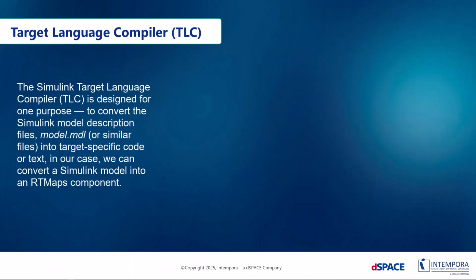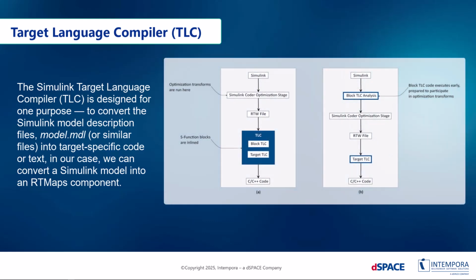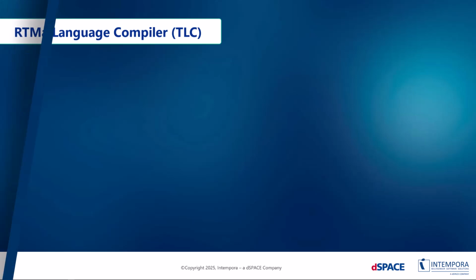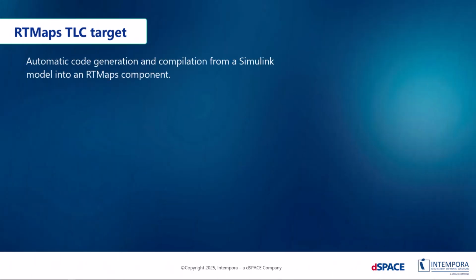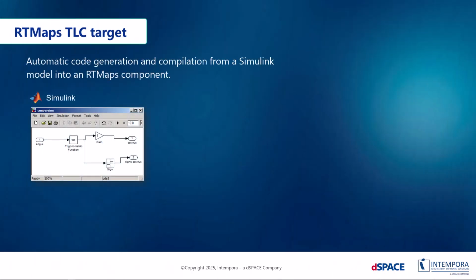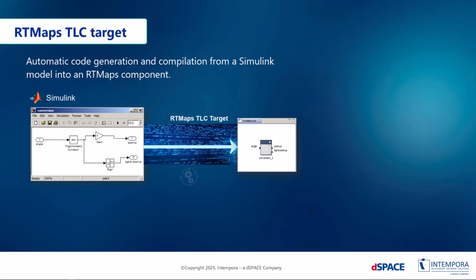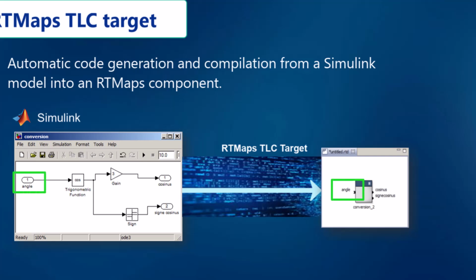The Simulink TLC enables the customization of code generation out of a Simulink model. Through customization, you can adjust the way the platform-specific code is generated. Generating RTMaps components from Simulink models allows you to easily integrate algorithms created with Simulink into a real-time modular environment adapted to the needs of robotics, automotive, and multisensor data processing.